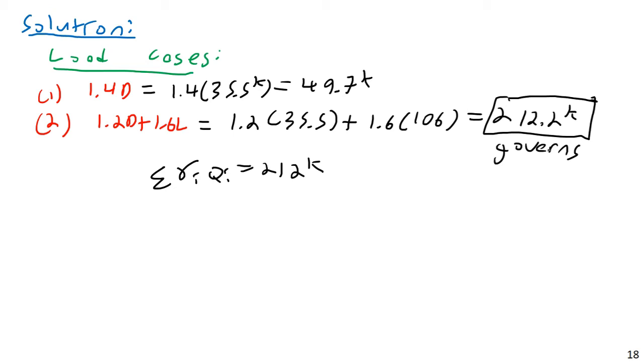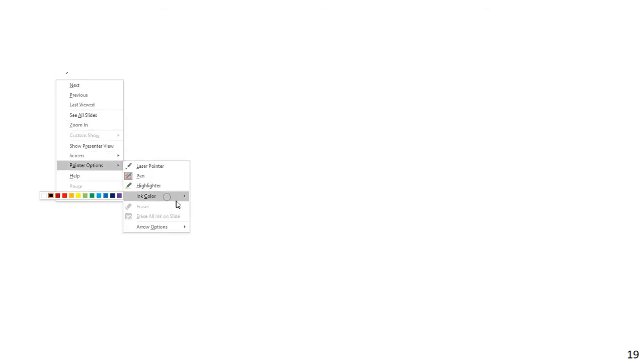And so this is our demand. And now we need to make sure that both our tension member and our connecting element are capable of supplying enough resistance to meet this demand. So let's first look at the tension member and the tension member limit states. Again, the tension member would normally have block shear rupture to consider, but the magical genie took care of that, so we don't need to worry about that for this particular lecture.